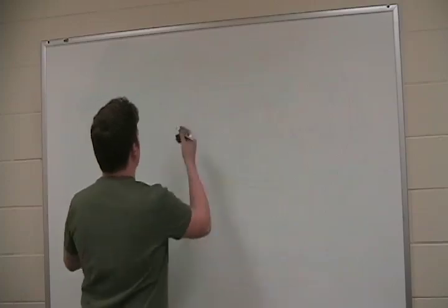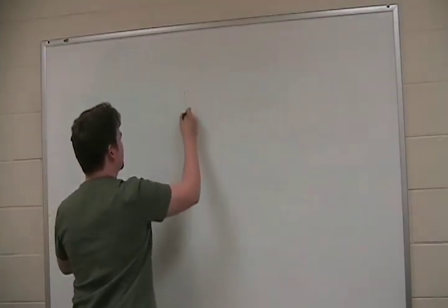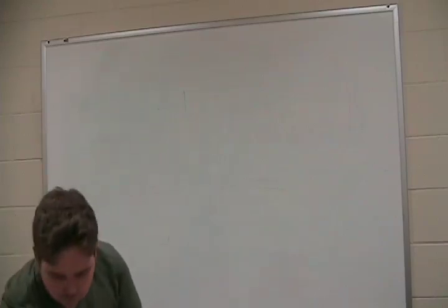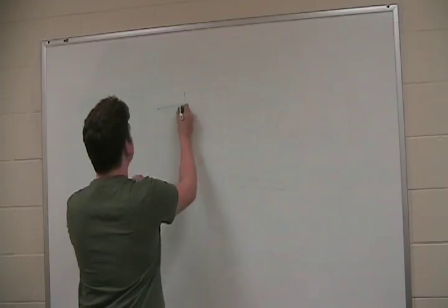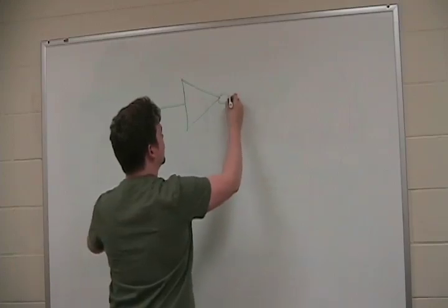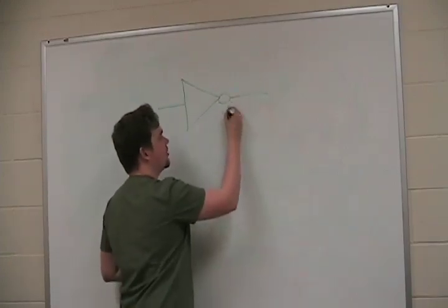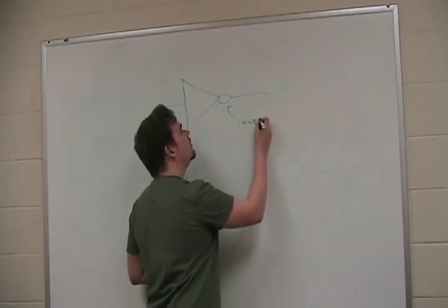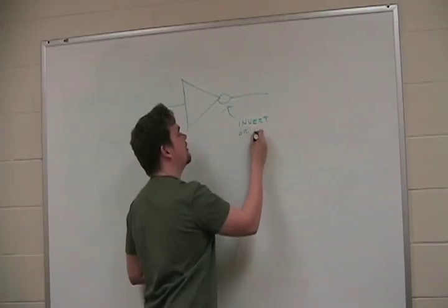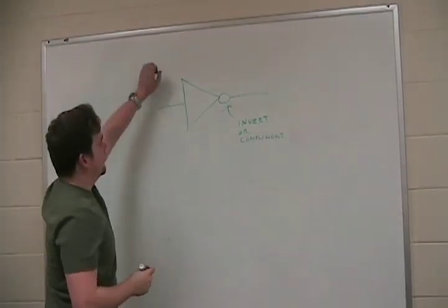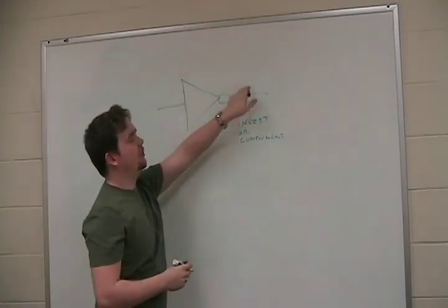First of all, we're going to talk about our truth table. We're going to look at our NOT gate again. Our triangle with circle on the end. Now keep in mind this little circle. That means to invert or to complement. Now what that means is that whatever digital signal is here, the output's going to do the exact opposite.